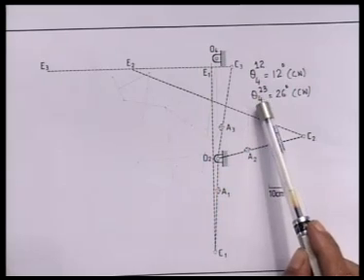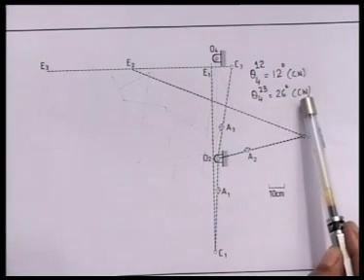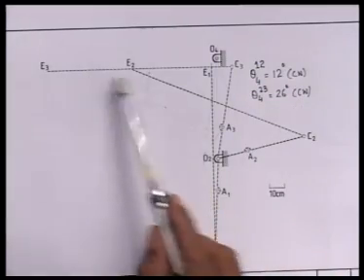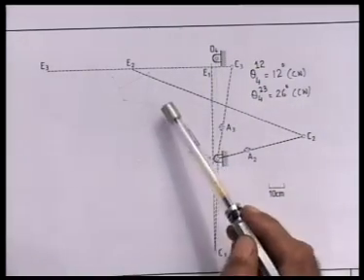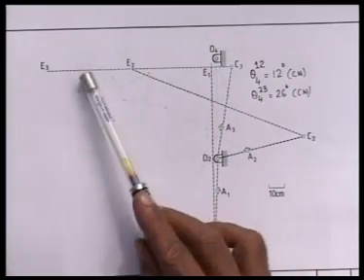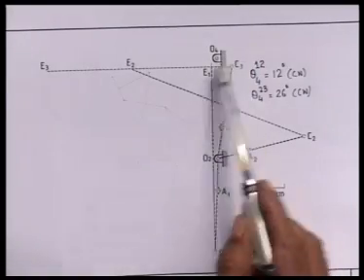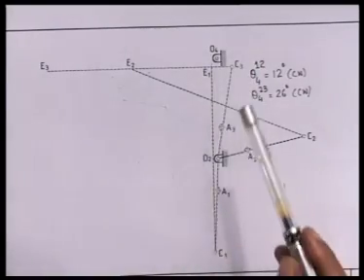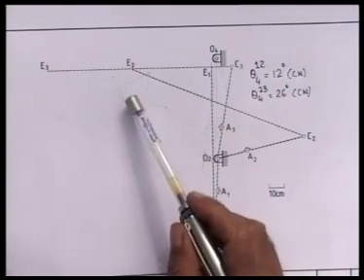Similarly, theta 4 2 3 is also prescribed that it should be 26 degree clockwise. Our task is to determine the rest of the linkage, that is the location of the second order hinge at B and also the hinge at D on this door board CE. And we shall determine the linkage at the 3rd configuration. That means we shall determine where is B3 and D3.